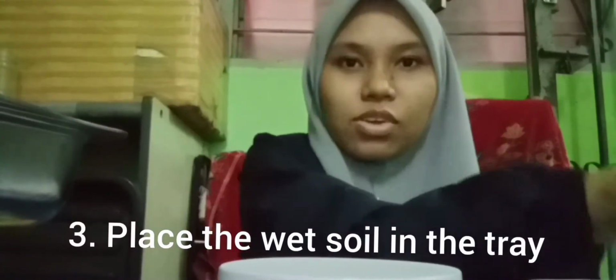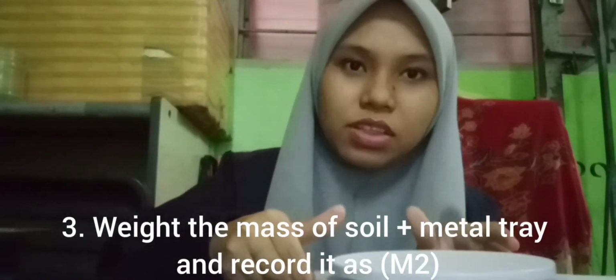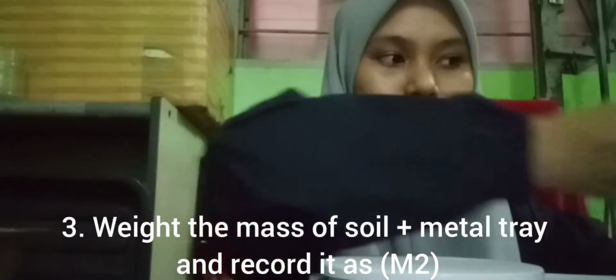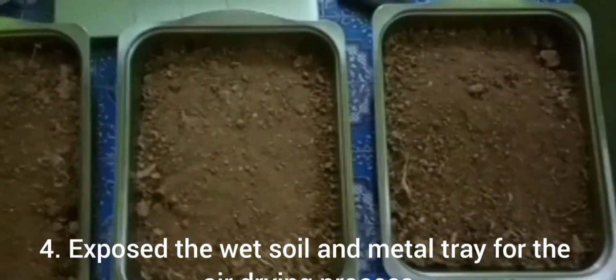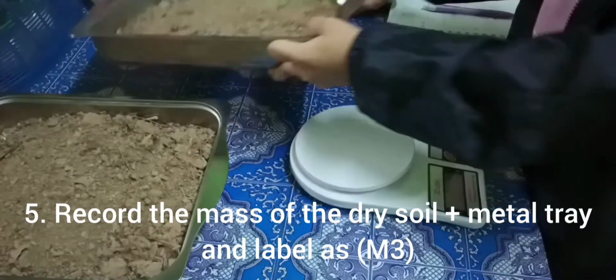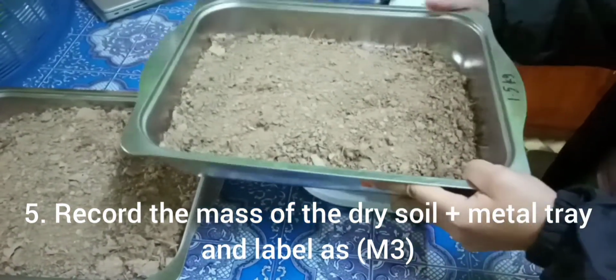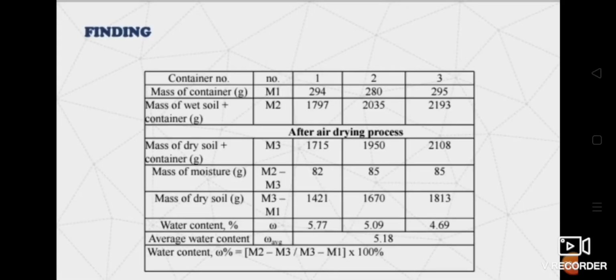Next, place the wet soil in the tray, like this. After that, weigh the mass of soil plus metal tray and record it as M2. Expose the wet soil and metal tray for the air drying process. After 24 hours, this is the dry soil that I get. Next, weigh the dry soil and mark it as M3. For the finding of the water content, I got an average water content of 5.18.